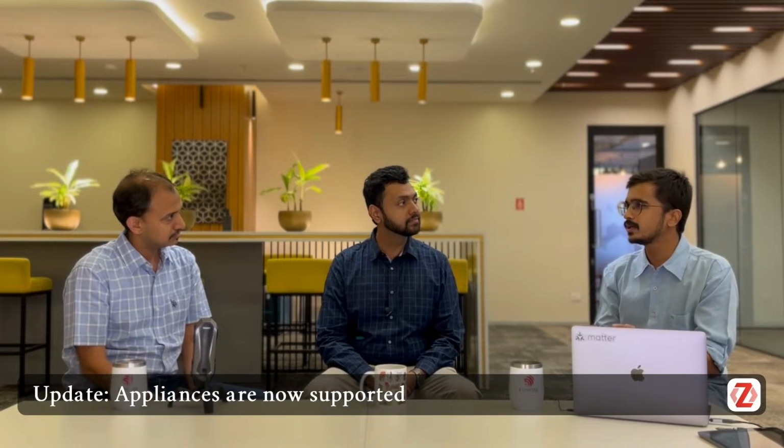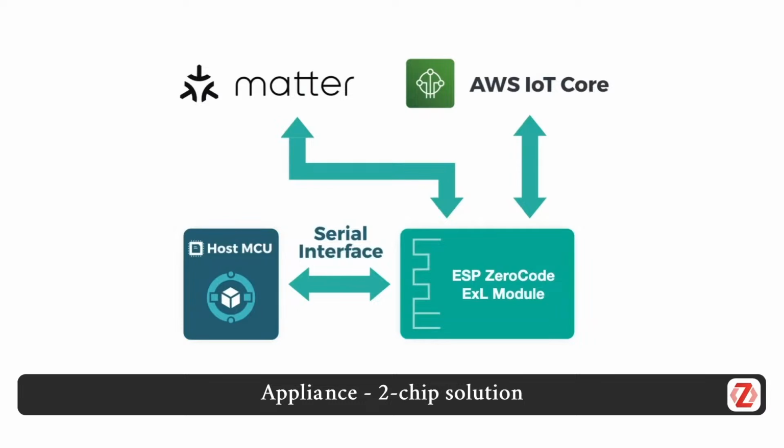It will typically be a 2-chip solution where the primary chip, which is the Espressif chip, will do all the heavy lifting of Matter and everything else, and the other chip, which is the appliance, will handle all the driver-specific things, because this is how the hardware design is in appliances, where they don't want to change the driver part a lot. A host MCU drives all the communication. In a way, the wireless MCU is different, and so this will be more like a Matter coprocessor, exposing its functionality over UART or something.